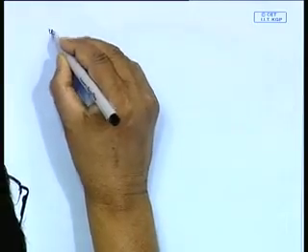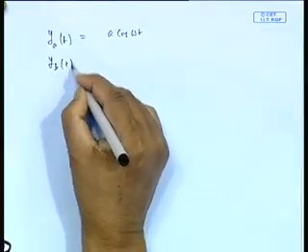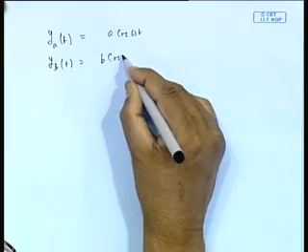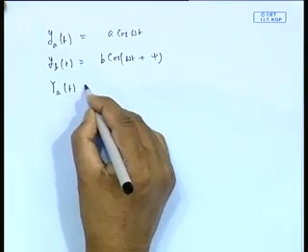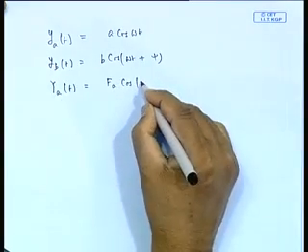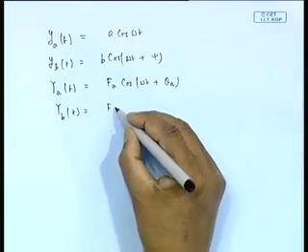See, here what I want to do, we have shown this separately, saying that I can do pure sway, pure yaw by taking this phase, etc. But the entire thing can come out in an equation form if I play with the equation of motion. For example, see here I have these two struts. The aft strut was given by a cos omega t. Forward strut motion is given as b cos(omega t plus psi), I am just writing a general expression, some phase gap there. I am measuring forces aft, it is coming out to be say f_a cos(omega t plus theta_a). Forward will turn out to be f_b